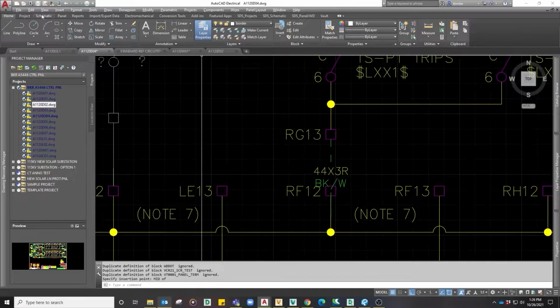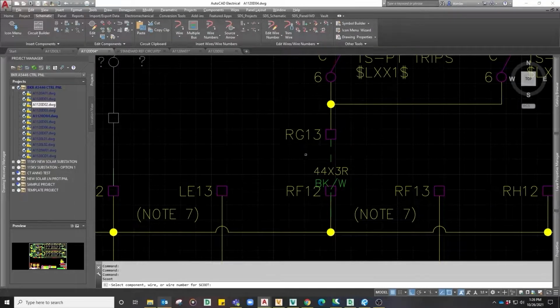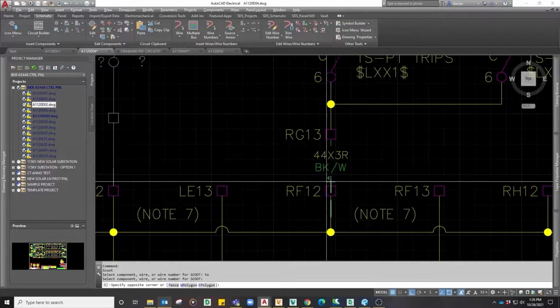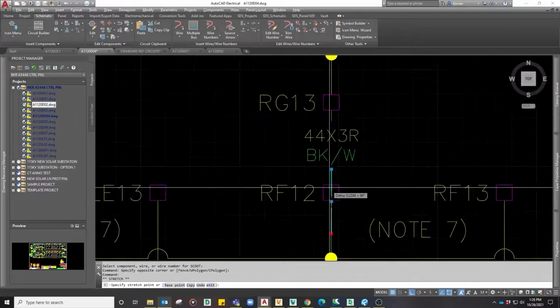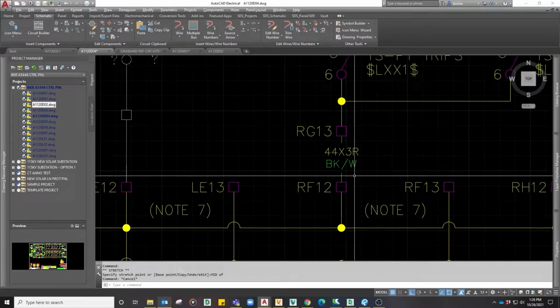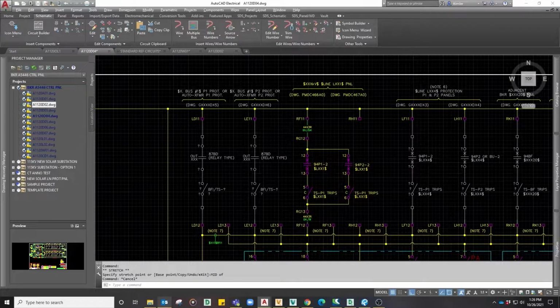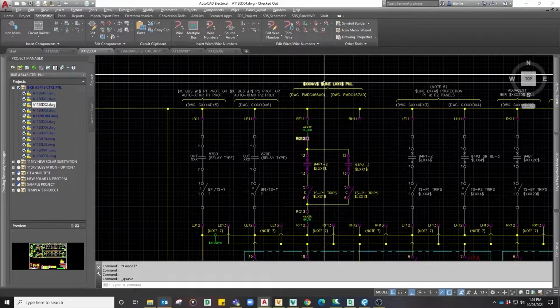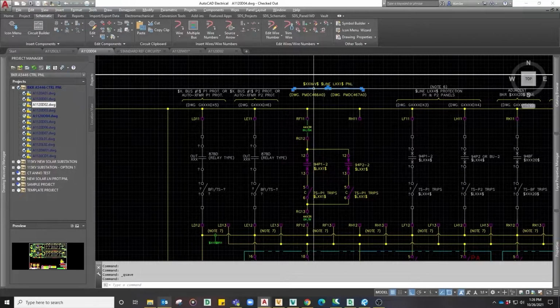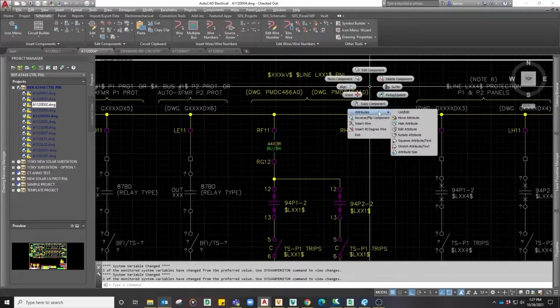So to fix that, I'll go to Scoot under the Edit Components tab, scoot my cable marker symbol up, and I'll also grab the grip of that wire and stretch it to snap to the midpoint of the schematic terminal. I'll move the bracket down and clean up these attributes to be aligned with the rest of the text in the circuit.